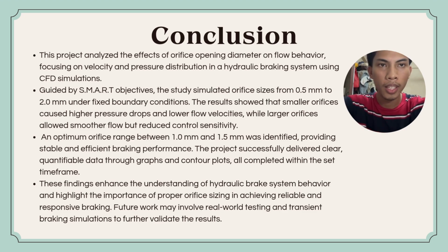Okay, for conclusion, this project analyzed the effect of orifice opening diameter on flow behavior, focusing on velocity and pressure distribution in a hydraulic braking system using CFD simulation. Second, guided by SMART objectives, the study simulated orifice sizes from 0.5 mm to 2.0 mm under fixed boundary conditions. The results showed smaller orifices cause higher pressure drop and higher flow velocities, while larger orifices allow more flow but reduce control sensitivity.